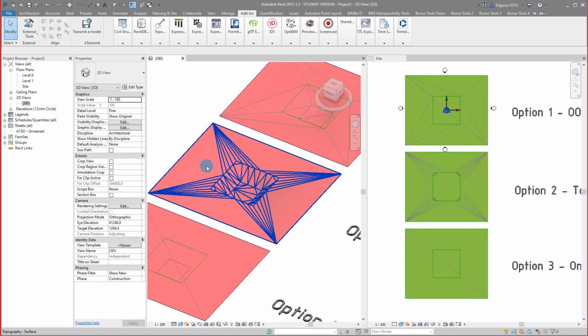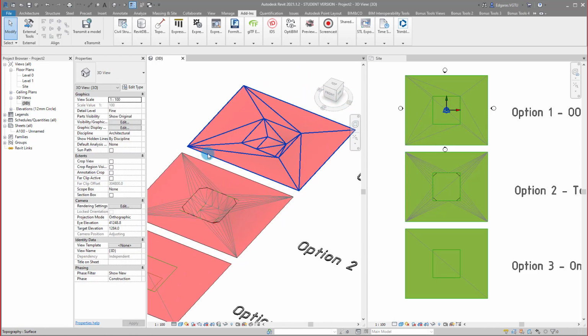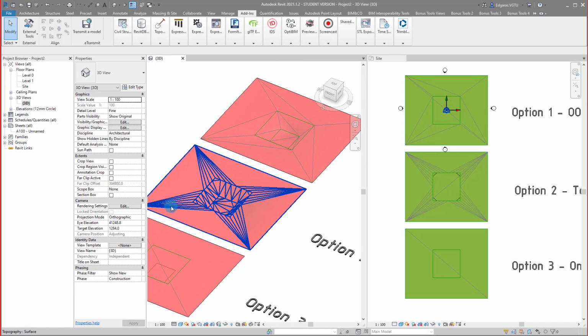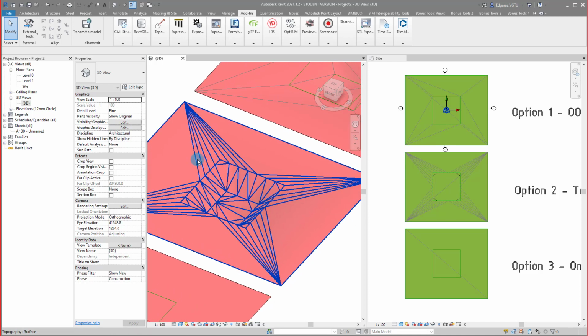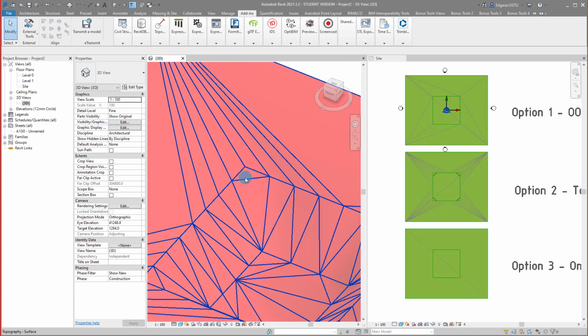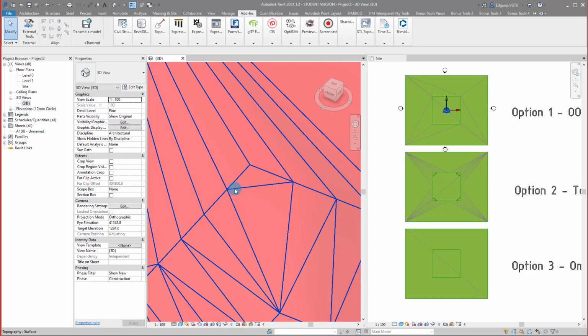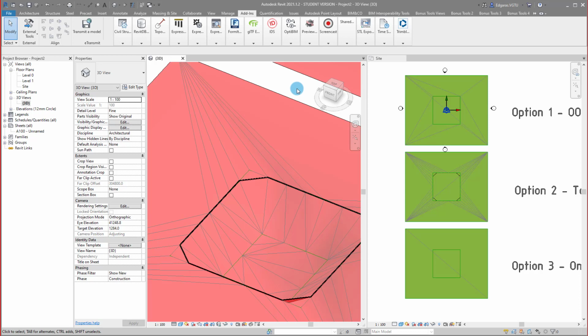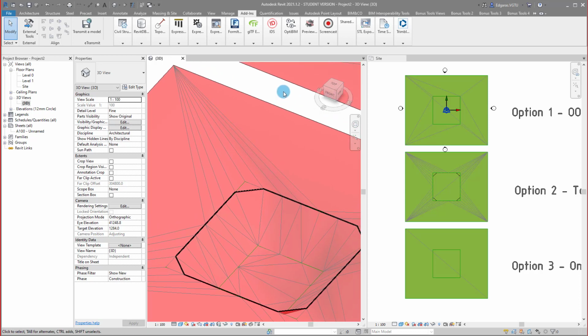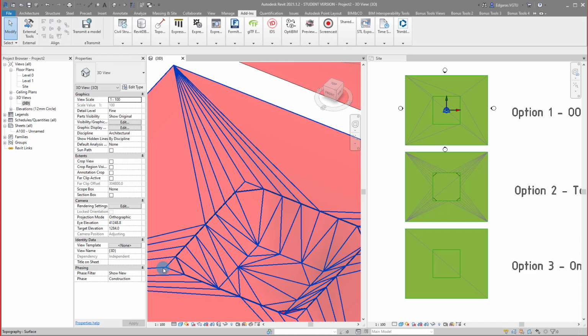Triangulation is the same from all the sides, comparing to out of the box example, and in this case I have more triangles because I have more points, and I have some problems in this location because I have an additional line which creates 2 triangles, and if I select thin lines, thick lines, you see my top surface construction pit is created not as I would like, so this line should go here.